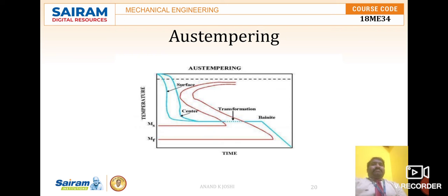And this bainite structure also has strength slightly lower than the martensite structure, but has better ductility and impact toughness. Since this steel does not suffer any severe quenching treatment, it is also less likely to crack or distort. However, Austempering suffers from a major drawback, okay.